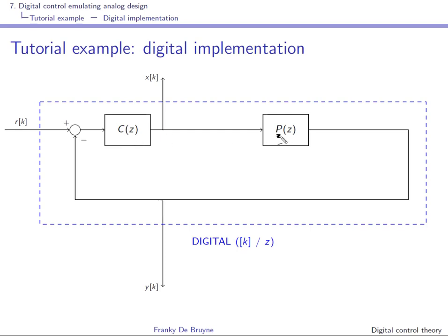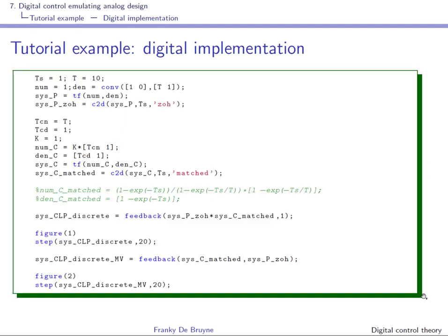So in Matlab, what we can do is simulate the system with our digital controller, and this one is here the zero order hold equivalent description of the process. So this can be done in Matlab. Sometimes it's easier to work in Matlab, but remember that the downside is that we do not have access to the intersample behavior. Well, this is the way to go in Matlab.